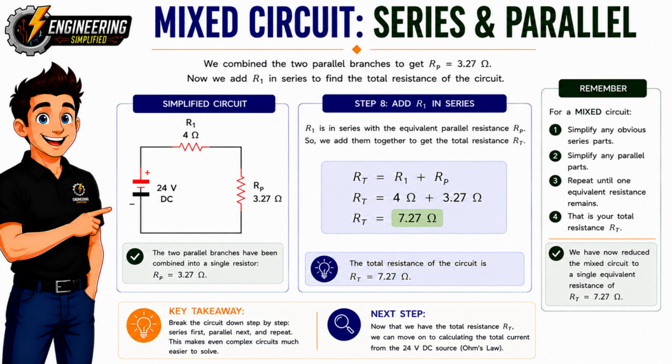Substituting the values gives us R sub T equals 4 ohms plus 3.27 ohms, which equals 7.27 ohms. And that's it. We've reduced a circuit that originally contained 5 resistors with both series and parallel sections into a single equivalent resistance of 7.27 ohms. This is the value the 24-volt power supply sees. Finding the total resistance is always the first major step when solving a mixed circuit.